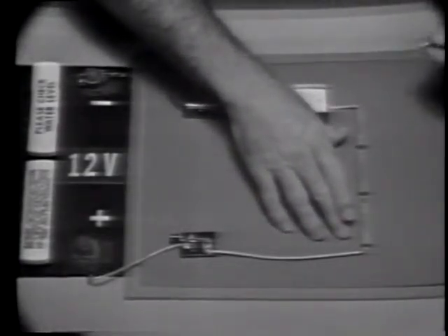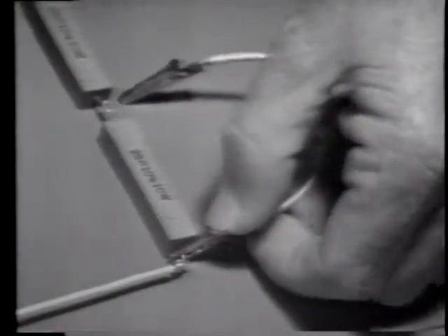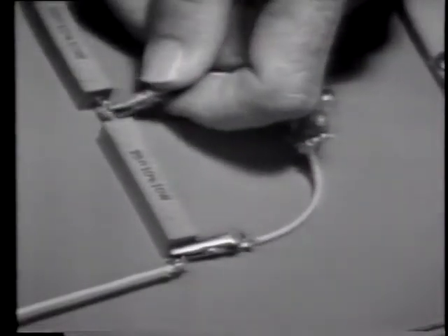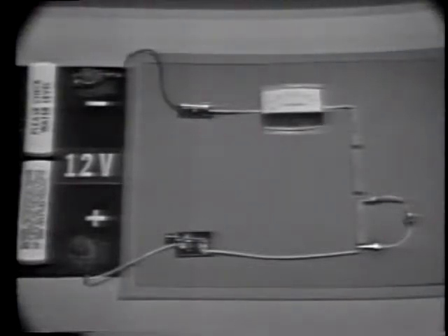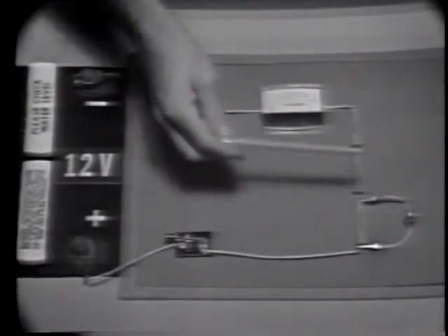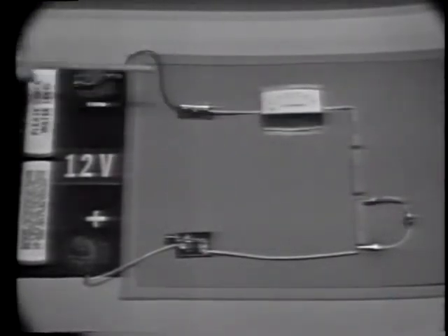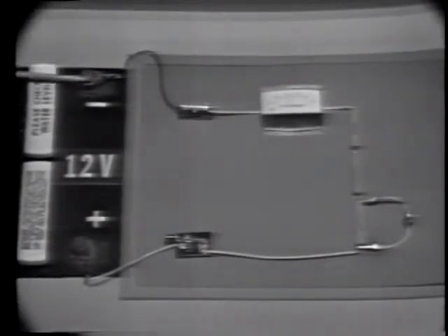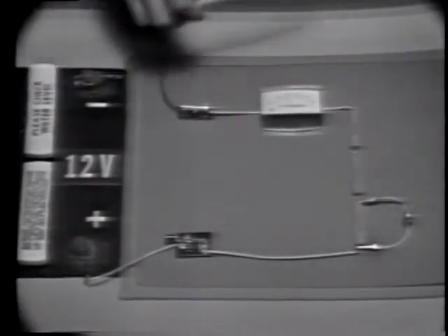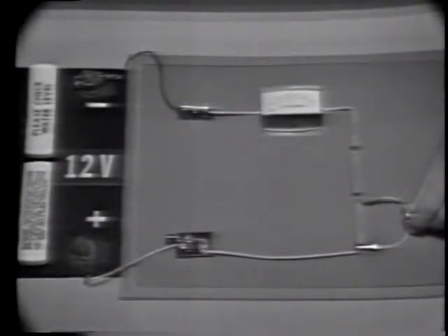Okay, let's use the voltage from the divider to do some work. Let me connect a bulb across this resistor. Now, when I make the connection, I load the circuit. Load means current. So when we load a circuit, we're demanding additional current from the power source. Of course, the component that we're adding out here would be called a load device. So keep in mind, load is current. The device that uses the current is called a load device.